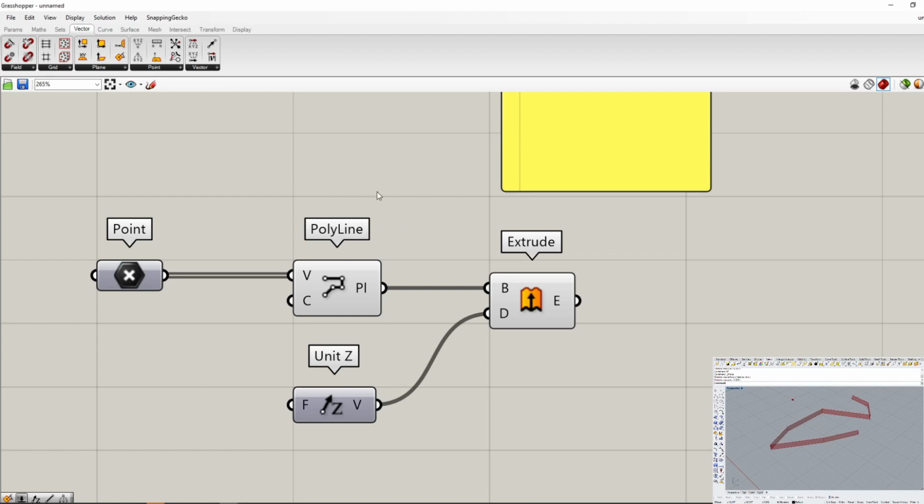So now we can talk about this stuff here. By default, we have draw shaded preview geometry set to on. The one to the left of it is draw wireframe preview geometry, which, you guessed it, will draw the geometry as a wireframe. And the final one is don't draw anything.